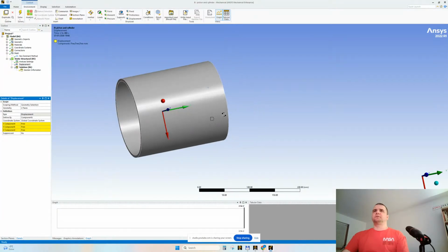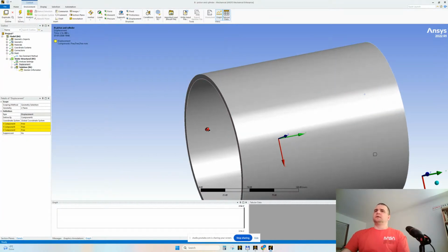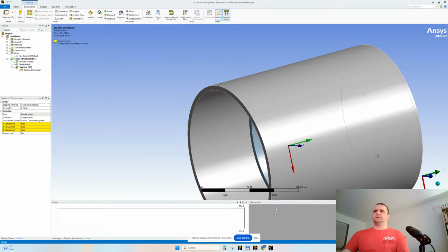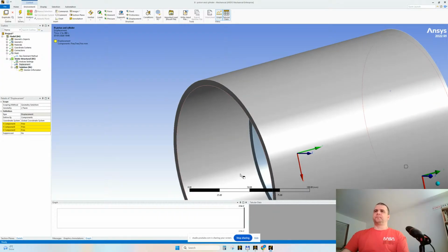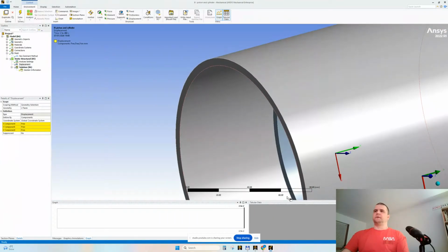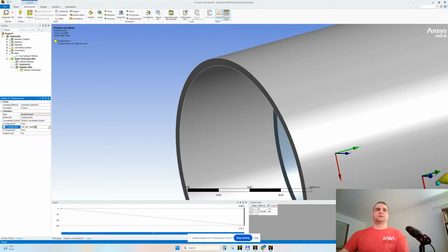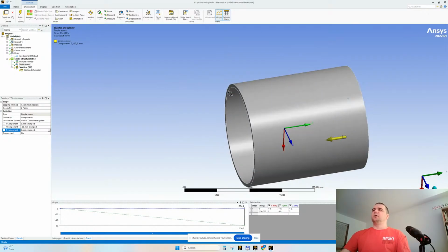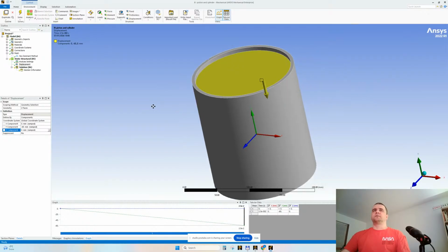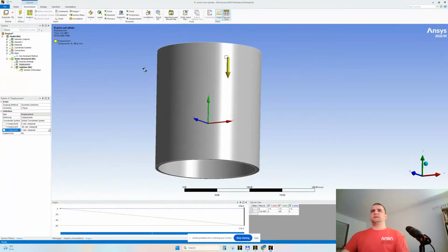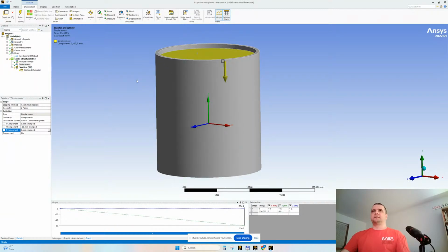Let's displacement on the y-axis with the value. I'm looking at the ruler here, and a value could be 60 millimeter, okay? On the y-axis, minus 60 millimeters. Do we need displacement on x? No. On z, no. We only need this axial displacement on the y-axis. All right. So we have a displacement. Let's fix.